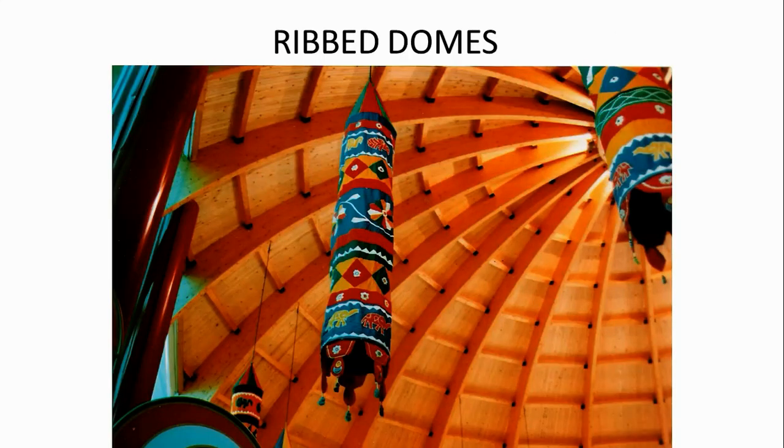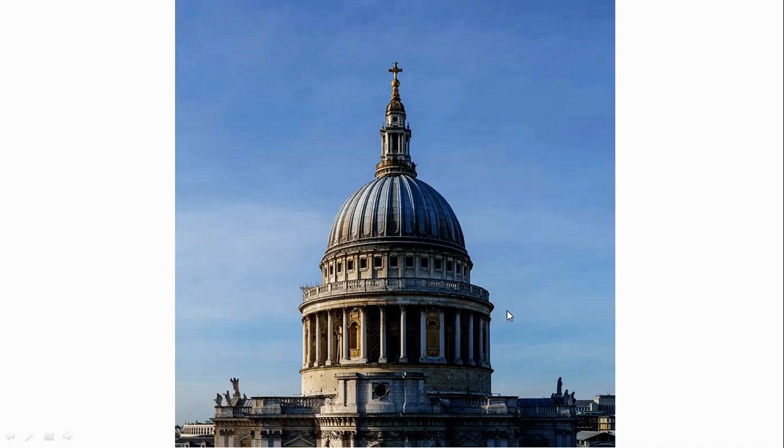If you rotate the arch, in the simplest terms, you start to develop domes rather than vaults. If you extrude the arch, you develop a vault. If you rotate the arch, you develop a dome. Here we've got a series of, these are actually glue laminated arches, aren't they? Glue laminated ribs. They're connected along the edge, because these elements are almost in pure tension, because they're just stopping the arch from splaying outwards. They're just connecting the ribs together.